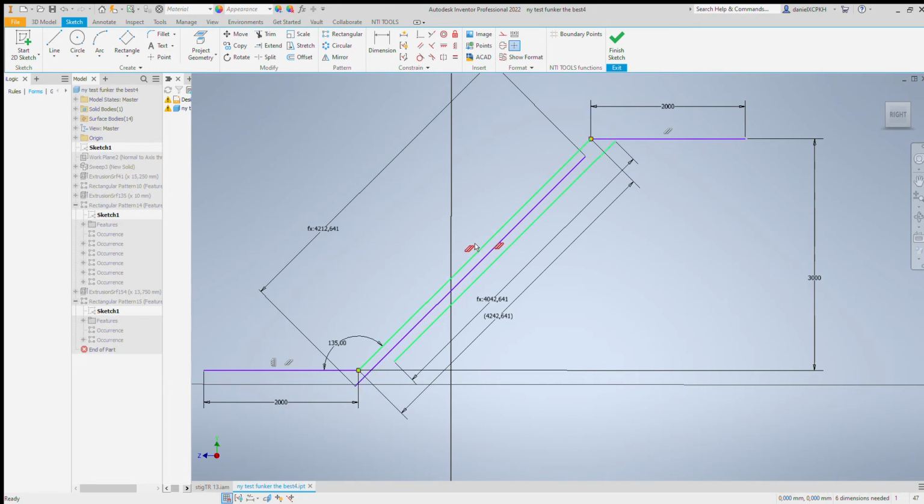Everything that drives the whole assembly is this height and this guy here. If you need to steer your pattern, we need to add a line like that here. After you add the line, just use these equal constraints. One click here, one click there. That's it. And this one here you call just hype.